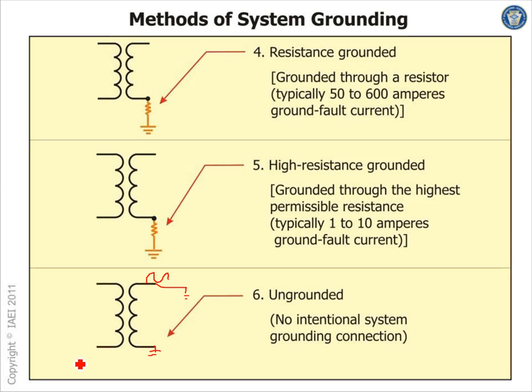Disadvantage, and I've been in a lot of companies where, if it's ungrounded and you happen to have a ground fault, it creates a transient that sits in your system and makes transient surges, which will burn electronic equipment, not the air handling unit, but the electronic equipment.